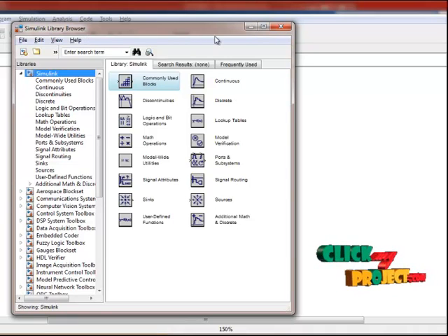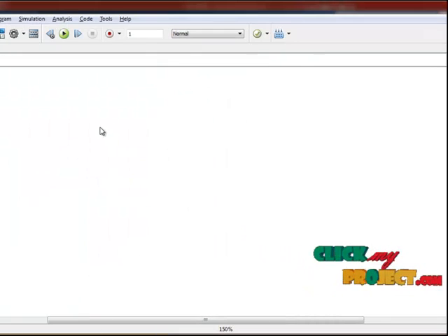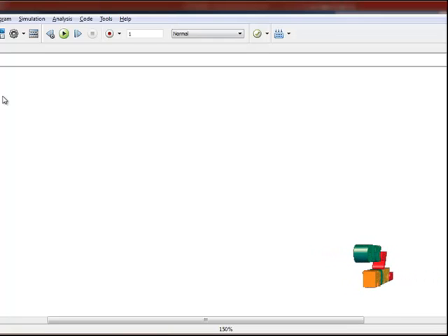After that, for the output results, we mostly show them using the scope model. The scope is available, and wherever we want, from one place to another, we connect it between the current and voltage measurement. We use the voltage measurement and current measurement tool devices. Connecting to the scope model, we get the output voltage, current and power, whatever we want to highlight in the scope model.